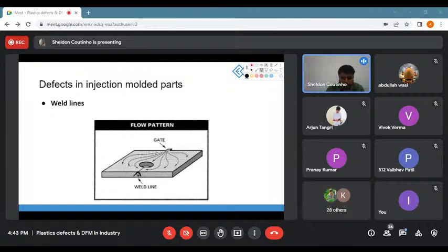Okay. Now, if I put the gate over here, where the plastic starts flowing, the temperature is going to be really high at entry. Since it traveled this distance, let's call this distance x. Let's call this 2x, for example. Now, this distance is barely 0.5x as compared to this. So if you understand, after traveling this distance, the plastic will start cooling at